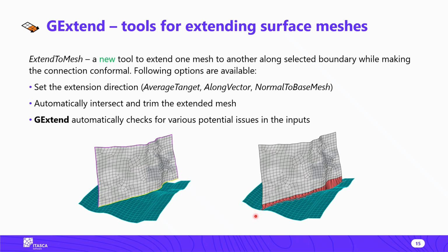In some cases, this unfortunately is not possible, especially when working with rather complex meshes, or if the target mesh already intersects base meshes, especially in multiple places. In this case, automatic intersection logic may fail. However, users can still extend the target mesh towards the base mesh without intersecting automatically. In this situation, use of GInt will be necessary afterwards, and with GInt there are more controls of how to do intersections and visualization, so users will have more options and see how the intersections will work.